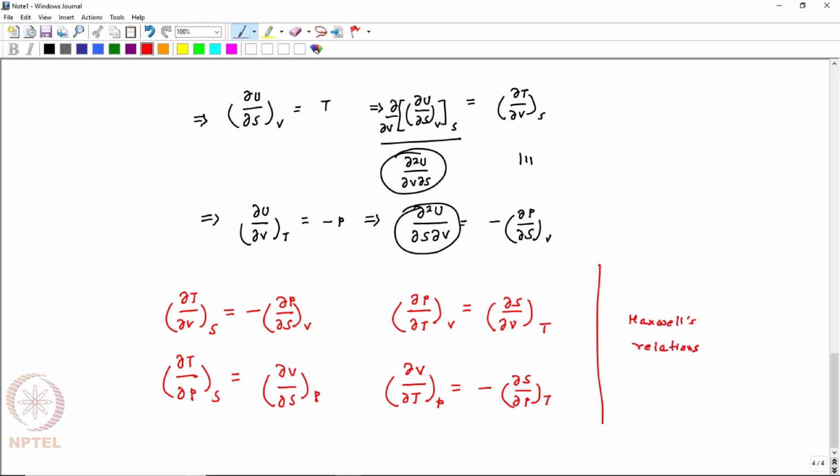and these are extremely important thermodynamic relations which we often use to derive many interesting thermodynamic properties. Now one thing we always want to keep in mind is that these equations were developed for any general system. But in order to actually apply these equations, you sometimes need the equation of state. You start from something and then you first focus on the process, like is it a reversible process or an irreversible process. If it is a reversible process, say for example, am I doing it in an isothermal way or in an adiabatic way.